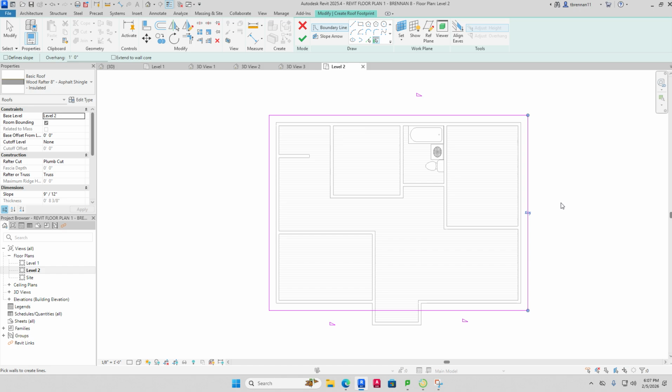Okay, now what we're going to do is touch this. Since we don't have a slope defined right now, click right here on this wall. Just go ahead and do that. And then we're going to put slopes on the porch. So this doesn't have a slope. Then we're going to go over here and define a slope one more time, which is right up here. You click this little box. You click on this wall here and that wall there. Now, that is exactly how we want it. The porch has slopes on the left and right, but the front is flat, and the sides are flat, and there's slopes the other direction.